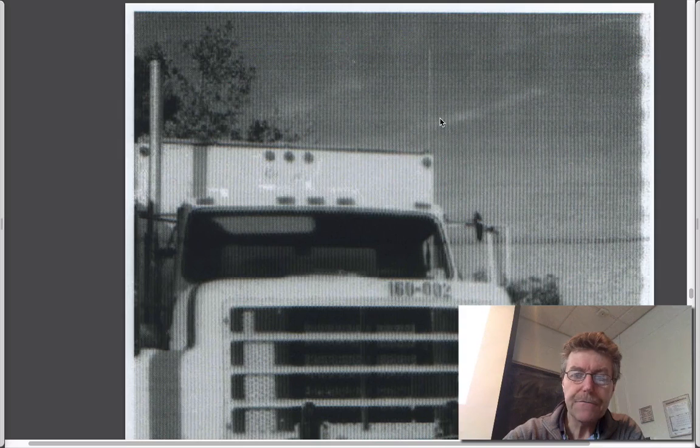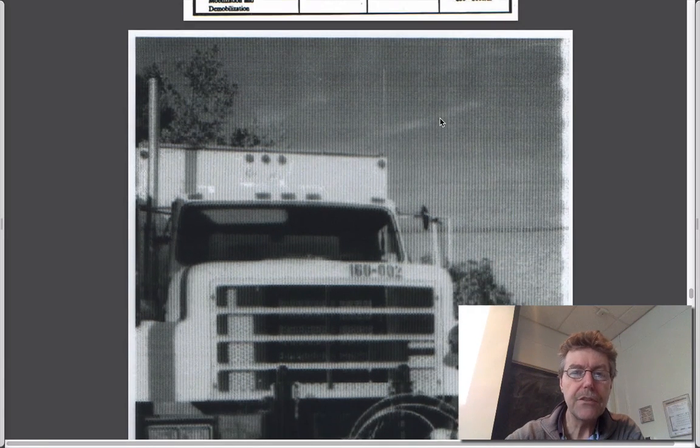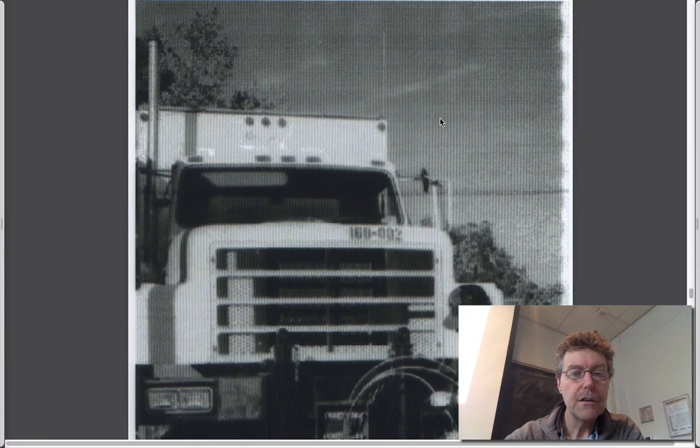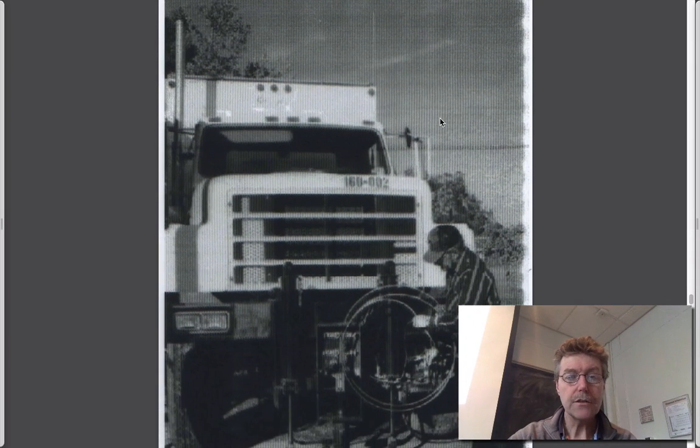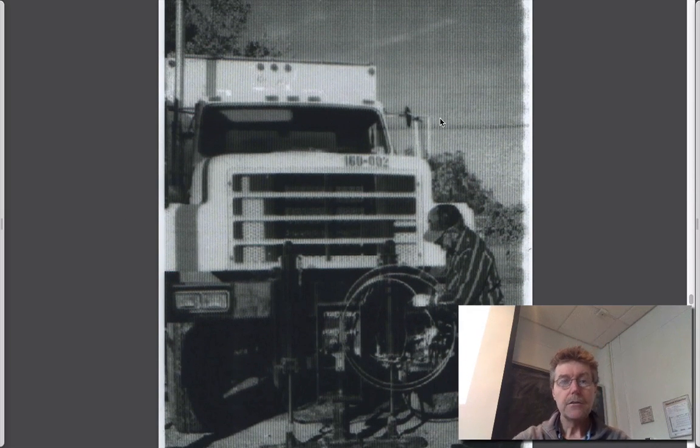But the other kinds of sampling, so we said that you can drill holes. The holes matter whether you're in soil or rock. It's either augers or rotary in soils. It's either rotary or diamond drilling in rocks. We'd like to sample from them. We'd like to instrument from the boreholes because we put something in place that is quite valuable to us.